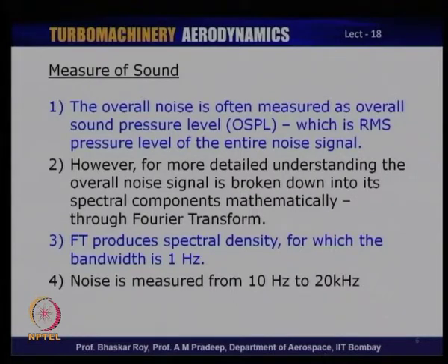So, any machine that you have, the simplest possible noise meter actually gives this value, where all the noise that is picked up by the measuring sensor is converted into an RMS pressure level, and hence it just gives an overall noise in decibels.